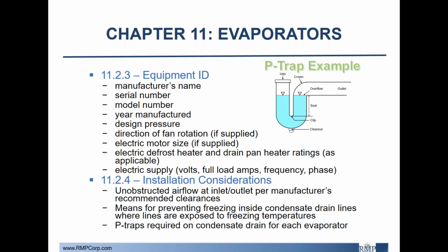For installation, always make sure that there's unobstructed airflow in the inlet-outlet areas per manufacturer's recommendations. They're really the experts on their equipment. They know how they've designed it, so always follow their recommendation or something more conservative than that.